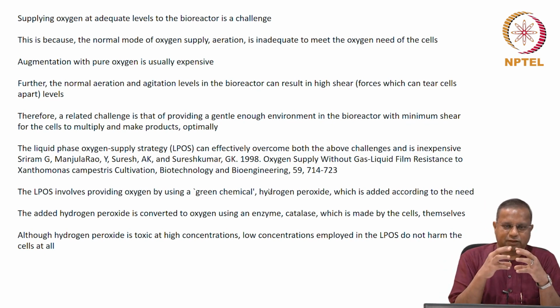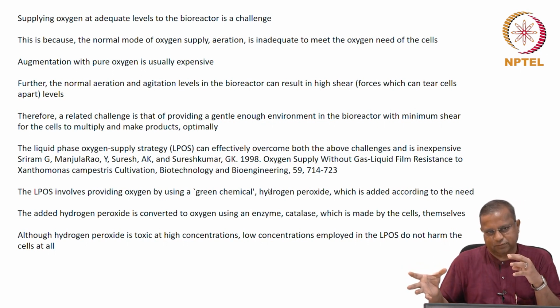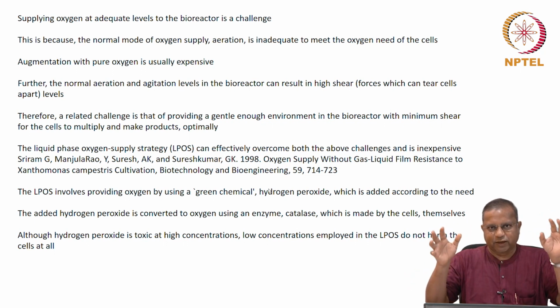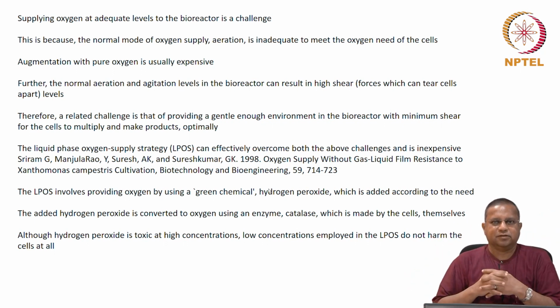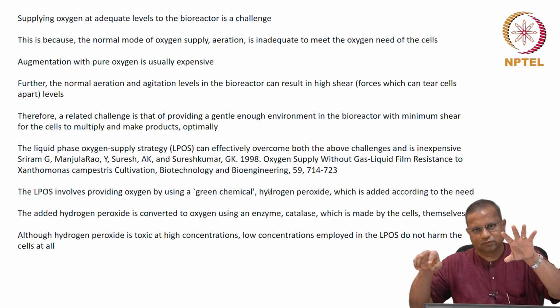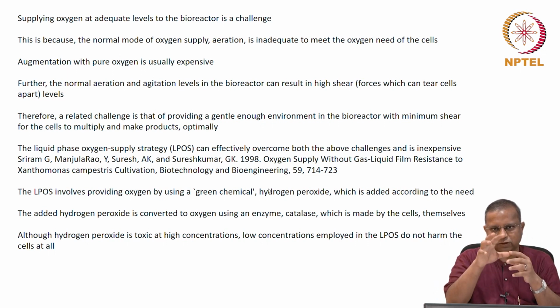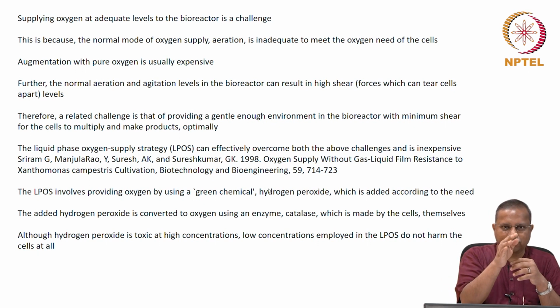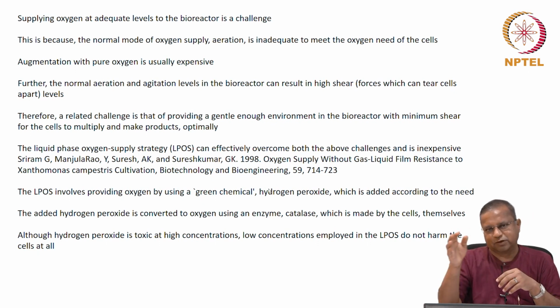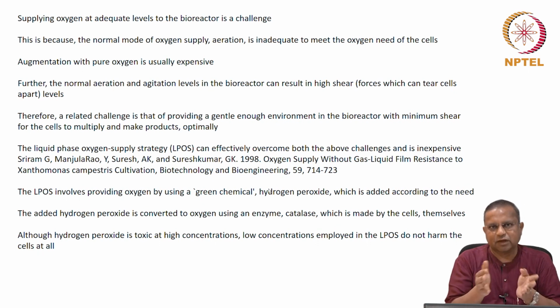See, we have the oxygen or the air bubble from which oxygen gets applied to the liquid, right? That's the case of aeration, the standard way by which oxygen is supplied. So here, you need to go from the gas phase to the liquid phase. In other words, you're overcoming a certain resistance. You can view it that way. You're overcoming a certain resistance for the transfer of oxygen from the gas phase to the liquid phase. And if you look at it closely, that resistance is the biggest resistance for transfer of oxygen in this situation.